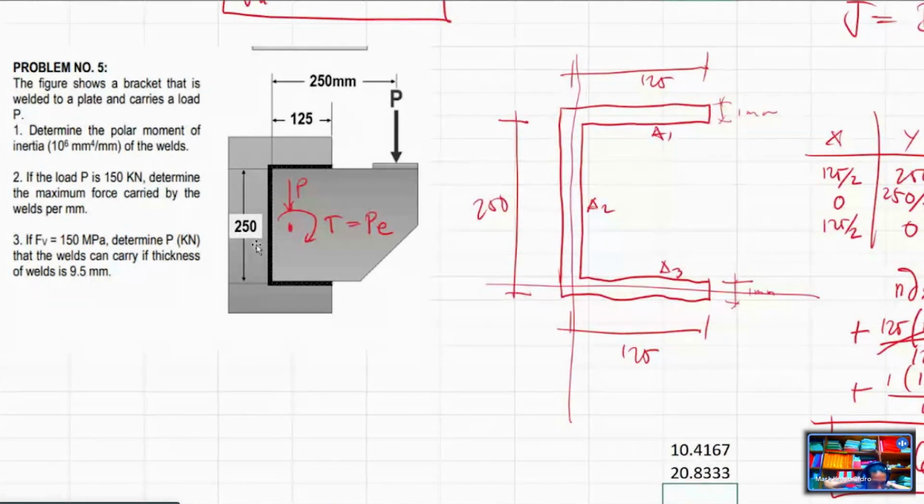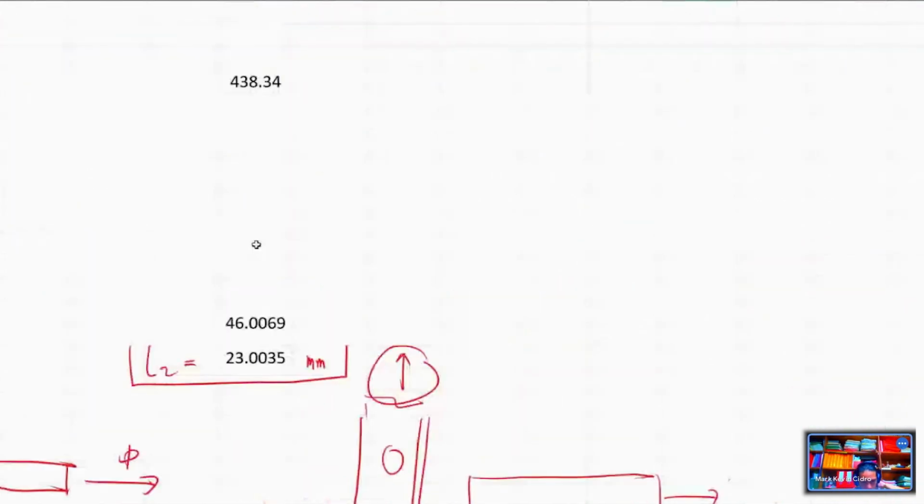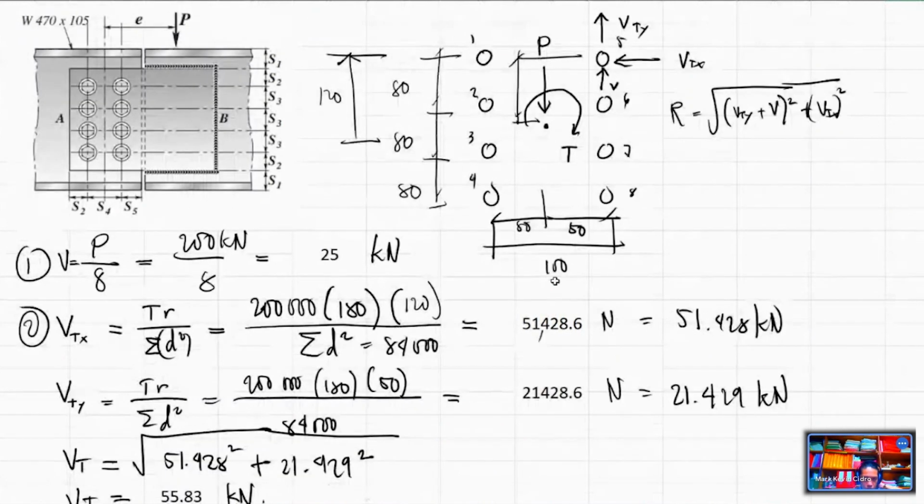What do you think is the answer? Recall the bolt we discussed earlier. This is the most vulnerable bolt, because all the forces acting on the bolt are not opposing each other, so they do not cancel out. For example, one pulls one way and another pulls the same way. So it is the most stressed bolt.